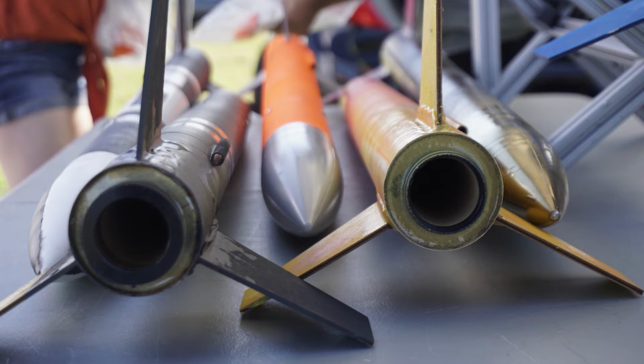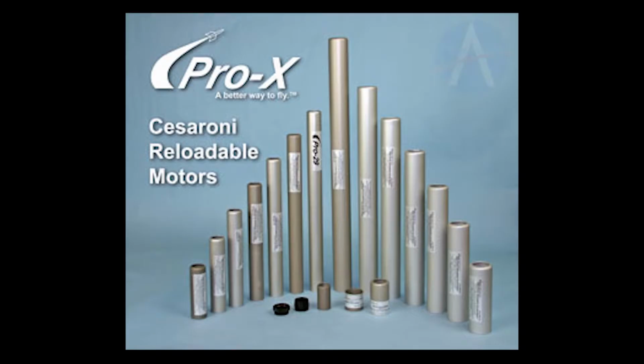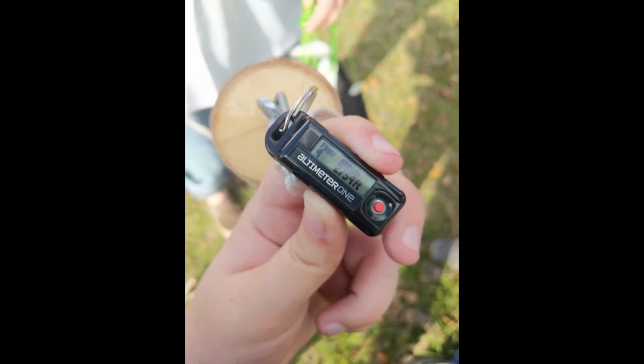The rocket used was built from a Loc Precision high-tech kit to the standards of the Rocket Association for Level 1 certification. It is a high-powered rocket and used a Cesaroni P38 2G White H110 motor and carried a small altimeter with negligible mass as the payload.